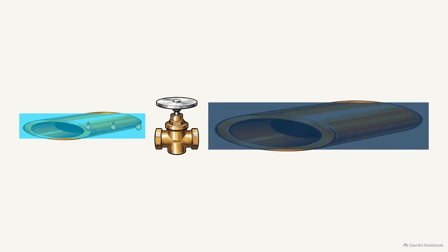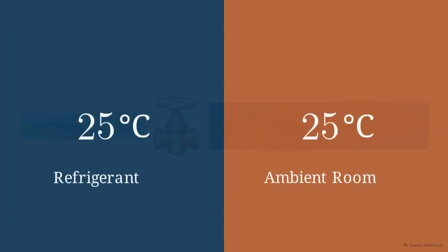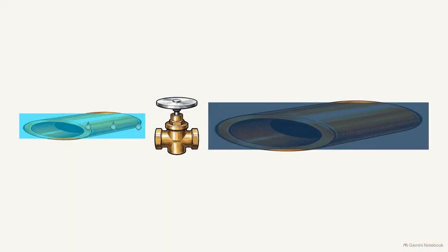Looking at a 2D cross-section of a copper coil, heat absorption begins when high-pressure liquid refrigerant reaches a narrow expansion valve. As the fluid squeezes through the restriction, it experiences an abrupt pressure drop, simultaneously forcing the saturation temperature to plummet. This sudden drop ensures the fluid's saturation temperature sits significantly below the ambient temperature of the target environment. The resulting low-pressure, low-temperature refrigerant then enters the empty volume of the evaporator coil.